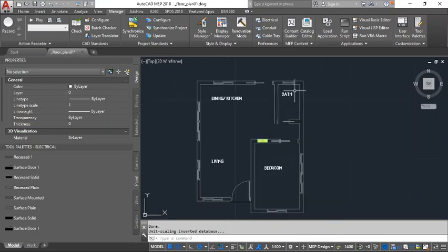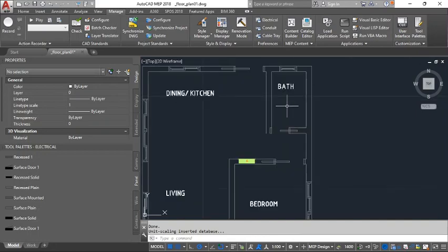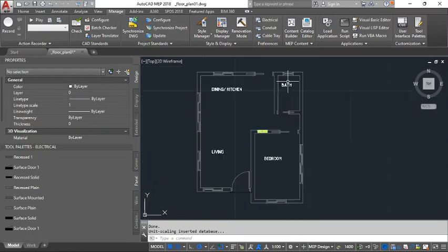Then we'll have a bathroom. We should give it a different circuit breaker. For the light and maybe the shaver outlet and all that, we can just put it under one circuit. We don't need to split the sockets and the lights because this is a very simple house.